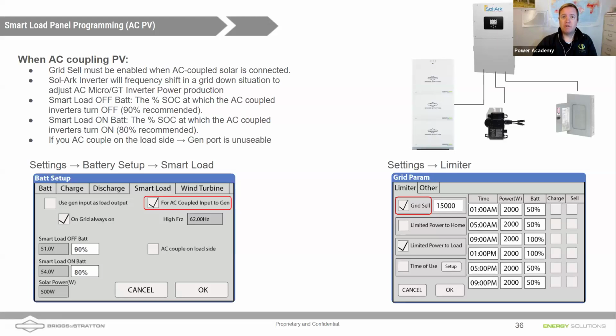Battery state of charge. So we're not at that upper limit. It does take a little bit of time, probably not as much time as I think, to be able to curtail some of that AC production by adjusting the frequency of the grid that we're forming inside the hybrid inverter to trick those microinverters into shutting themselves off.